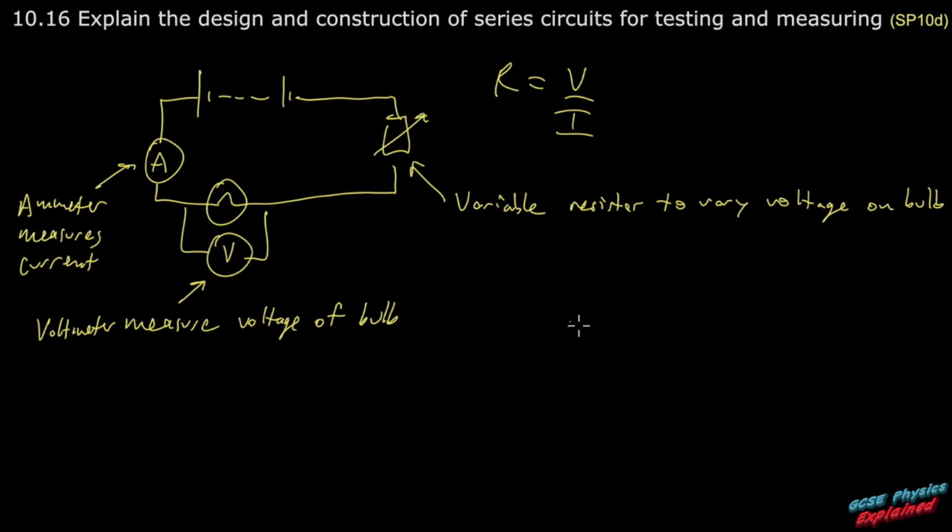Now what you'll do after that then is they'll very often ask you to do a current voltage graph. So what you tell the examiner is start off with this resistor small and make this resistor get bigger and bigger and bigger, and as you do, keep taking measurements of your voltage and your current across the bulb, and you'll end up getting enough results to create a graph.